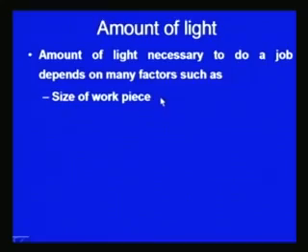The size of the workpiece is the first factor. In general, reduction in size increases the requirement of light, meaning the finer the job, the greater the amount of light required. It may go up to 1000 to 3000 lux, while for a coarse job greater than 1 mm, even 200 or 300 units of light may be enough.